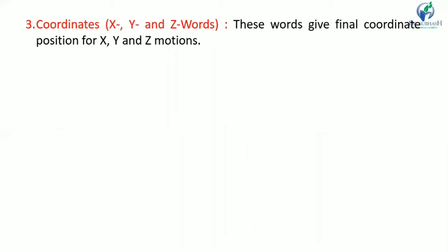However, some CNC control systems accept the decimal form. So we will adopt this convention for expressing the data in decimal form. While giving the data, positive sign is optional, but negative sign has to be given in case of negative dimensional position. Okay, you may write plus sign or not, but for the negative, compulsorily you have to write the sign of minus or the negative.